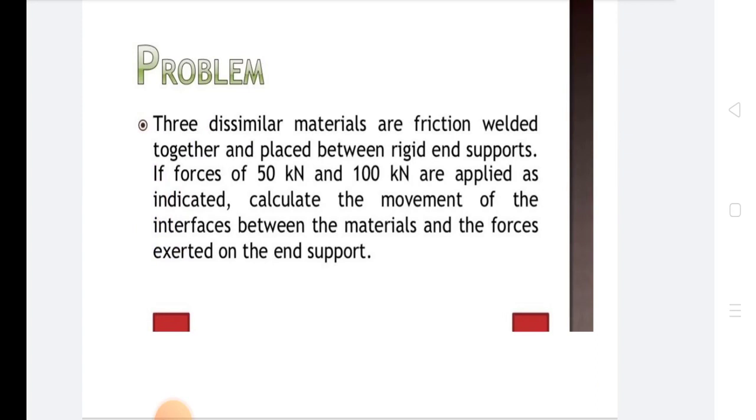The continuum, initially having infinite degrees of freedom, is discretized into n number of triangular elements having 6 degrees of freedom, as shown. The figure shows the triangular element having x displacements q1, q3, q5 and y displacements q2, q4 and q6. This is the very simple step 1.